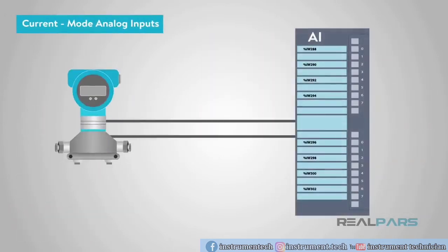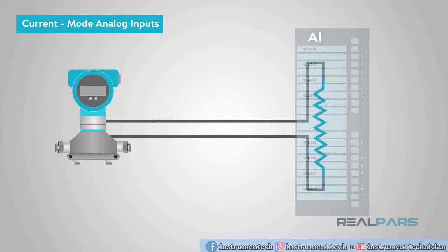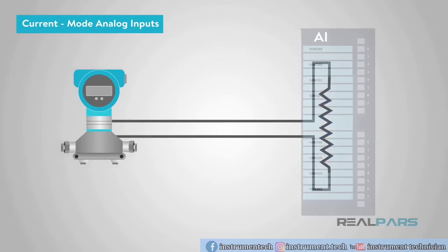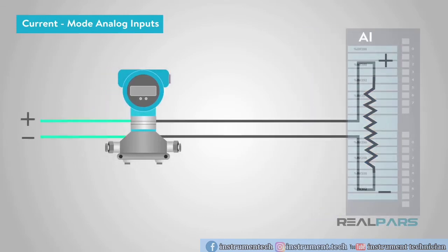While the voltage input is capable of almost everything we need in general applications, because of electrical noise interference from other devices, current mode signal transmission is a better choice for signals that need to travel over any real distance. For this reason, many applications use current inputs. From the PLC end, a current mode interface is generally a voltage mode interface with an added high-precision resistor. While the resistor is often inside the PLC module and switched in by a jumper or connection position, it is effectively the same. This is an example of a device-powered current source.